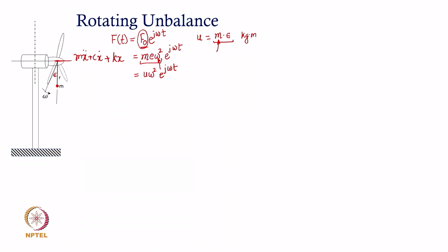Usually it gets a bit misinterpreted as the mass of the system. So, let us be clear that this mass can be any value, not necessarily the mass of the system. Although it is true that for the sake of convenience we say that the entire mass of this rotor is offset at a distance of epsilon, then things become a little easier and simpler to work with.